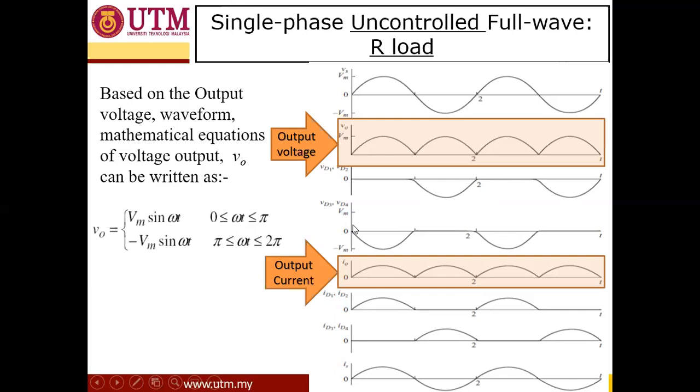This one is also the voltage across diodes 3 and 4. During the positive cycle, D1 is on while D3 and D4 are off, so a voltage blocking waveform appears here, and the maximum value is equal to negative VM of the source. And during the negative cycle, D3 and D4 are on, so we have no voltage drop.